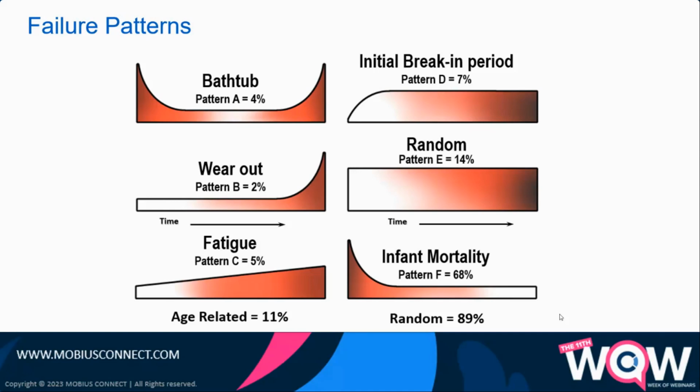So when you think about that historically, and what I've seen in my 35 plus years in industry and maintenance and reliability for a good portion of that, is that many maintenance strategies, most of them, are heavily designed around time-based maintenance strategies, and you have to ask the question, how effective really are they? Well, one would think somewhere around below 10-11%. So it's important to understand failure patterns as you're designing a maintenance strategy, because that really is a key enabler to pick the correct strategy. Next slide, please.